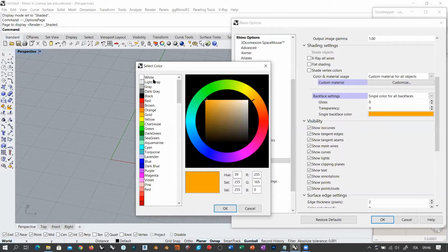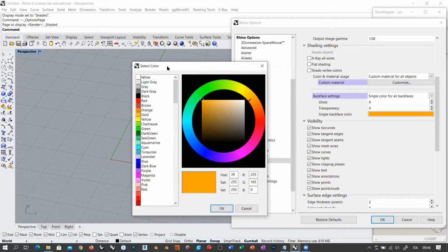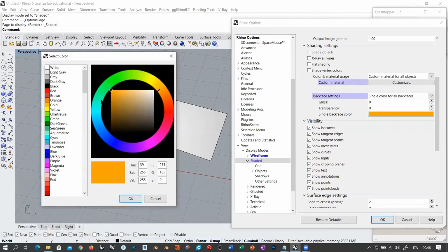All of these that have names, don't use them, because these are directly accessible also, for example, in the layer color configuration. And you might have some difficulties in understanding if you are looking at the negative face of an object or at an object that belongs to a particular layer and therefore has this kind of visualization color. So just drop down this list and pick one of these dumb colors that you have here at the bottom.